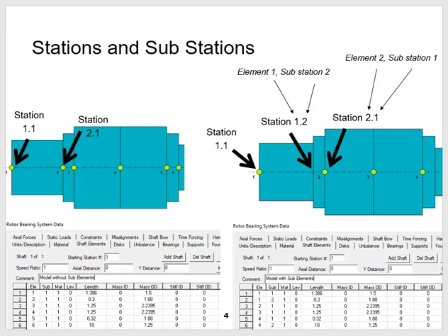Two methods are shown on the screen for modeling the same piece of a shaft. The method on the left does not use any subelements, and the method on the right does. For each model, the shaft element sheet is shown below. The two cases produce identical results when an analysis is run, but the case on the right is solving a more condensed set of equations.